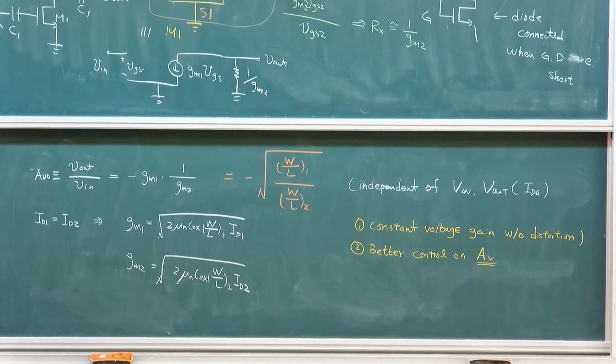I would like to, if you ever go into discussion, and we're actually going to skip that part, chapter 8. But what happens is that in typical operational amplifier design, you make sure the gain is large enough, and you don't really care exactly what it is. Just make sure that the gain is larger than 1,000, for example.